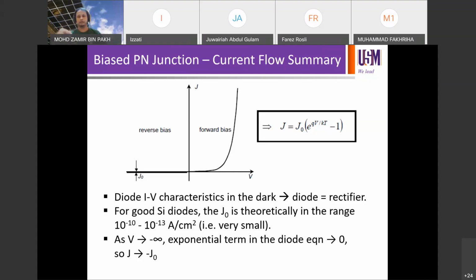When you look at the forward bias region, you can just see that the current increases exponentially when the voltage is high enough, and the current is very low in the small negative region in the reverse bias. But when you learn about this course, now you know what is actually driving what you see on the graph. So for example, if you're applying the forward bias, we are actually reducing the effective barrier height at the PN junction region, or at the depletion region, to be more specific.